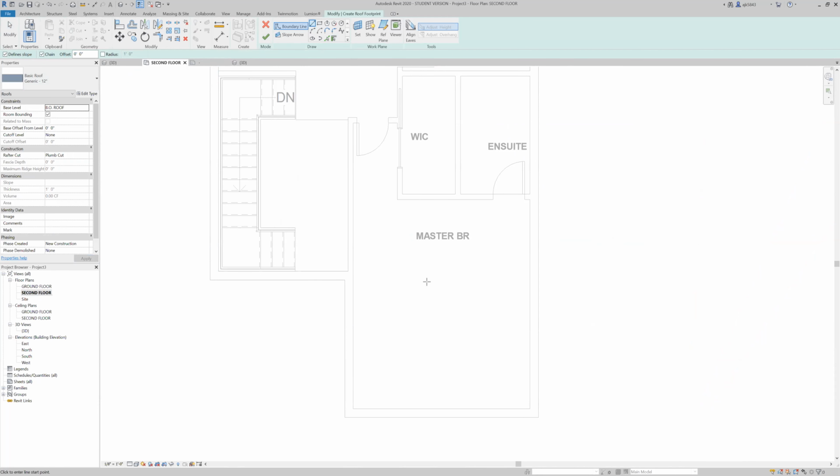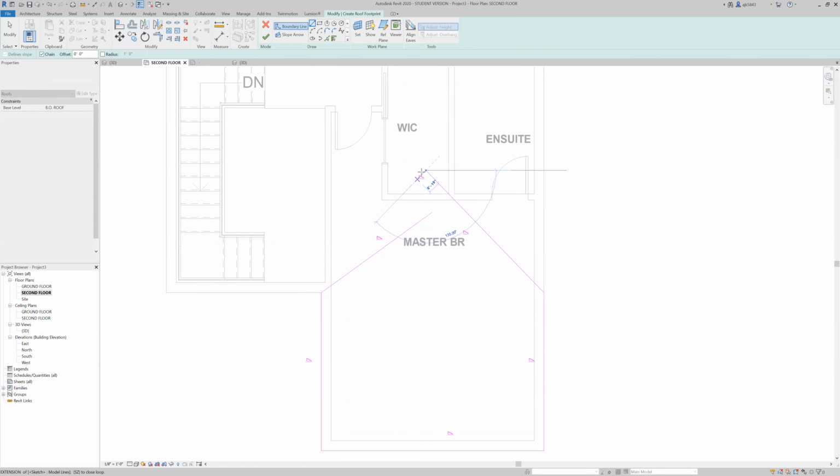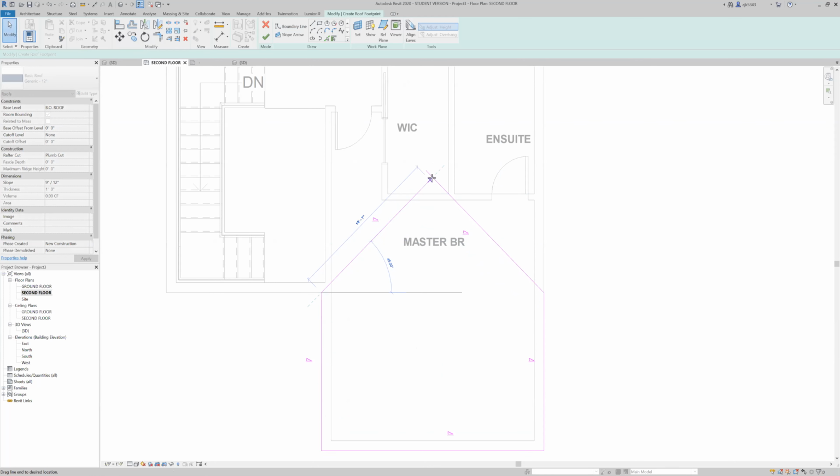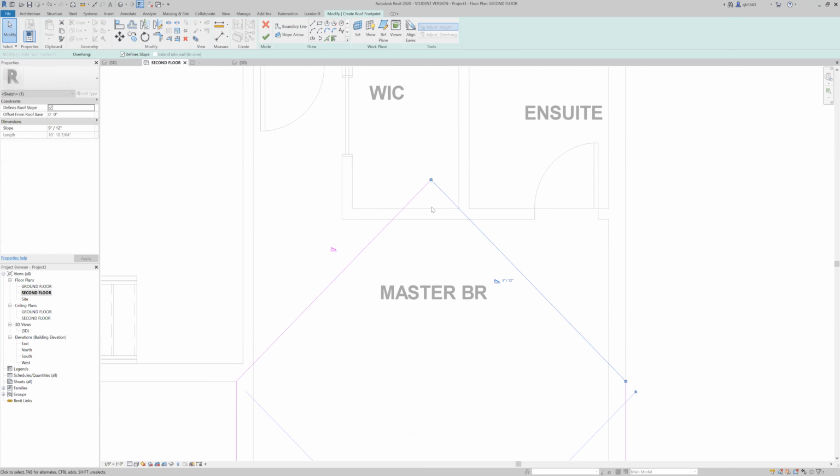I'm going to use my sketch line here and pull this right up into that corner. And then I'm going to define my two bottom boundaries and bring this up to where it's going to hit right there on the left side. Then I know that I was drawing at a 45-degree angle, so I can essentially just draw two 45-degree angles. In this case, they're at 135. You drew the first one at 35, not 45. There we go. So where they intersect, I'm just going to go ahead and pull these back to trim them in a little bit.